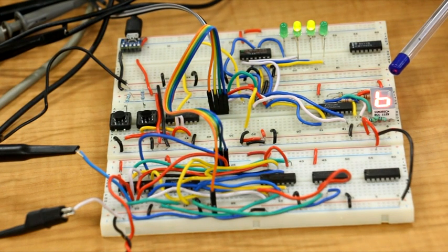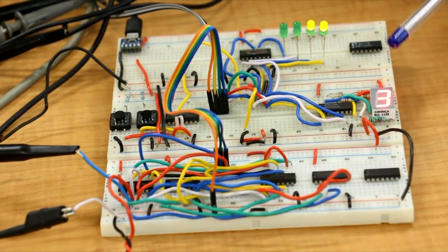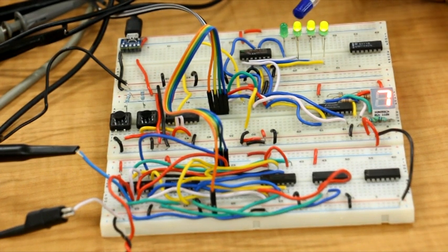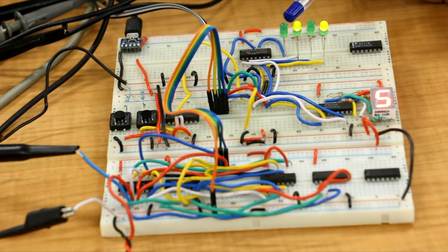So you see that the states 0, 0, 1 and all 0, 0, 0 are missing. And with these logic probes you can see the corresponding binary output. You can see 5 corresponds to 101, 4 is 100, 3 is 011, 2 is 010, and 7 again 111, and so on. So this works very nicely.